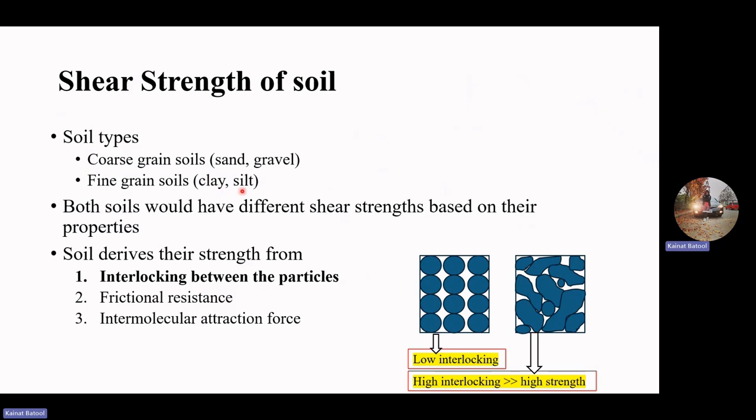For silts, there's another certain differentiation, which is that they are smaller in particle size than the clay particles, but they also depict some properties of sand. For example, if I say a liquid limit property, it would be more towards sand behavior than clay behavior, right? Also, most of the time coarse grain soils would have a particle arrangement like this, and the particles would be rounded surfaced. But in the fine grain soil there would be more flocculated structures, and the interlocking would look like this.